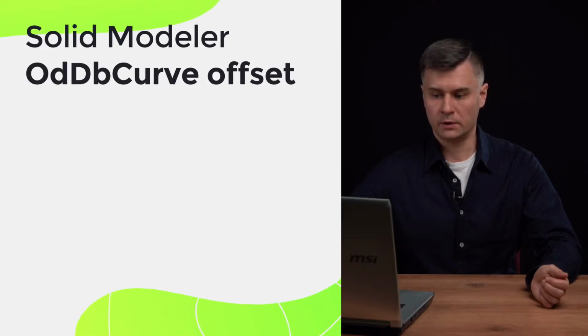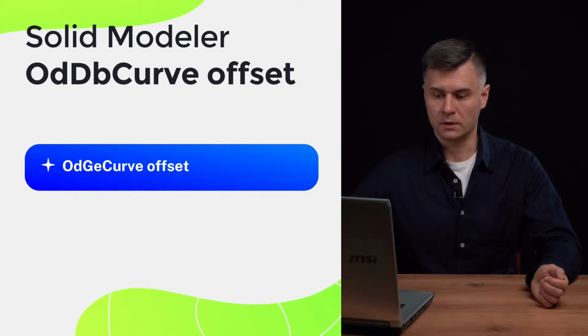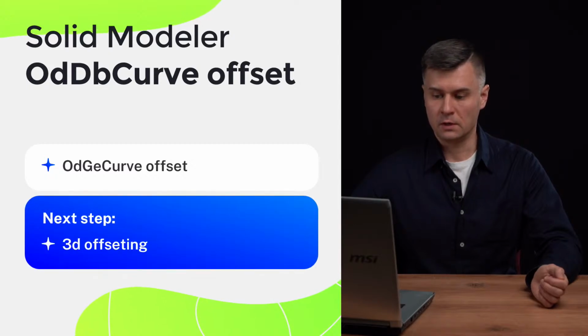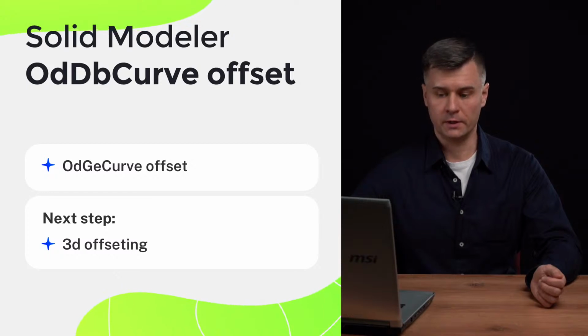Next item, ODB Curve offset. ODB Curve now supports offsetting functionality using the method getOffsetCurves. It creates a new ODB curve which lies within the offset distance from the original curve. Method getOffsetCurves, given a plane normal, allows choosing the offset direction. The offset feature is also available at kernel level as part of the geometry library, so it is available for all ODE products. And now we'll have a short video illustrating this capability.